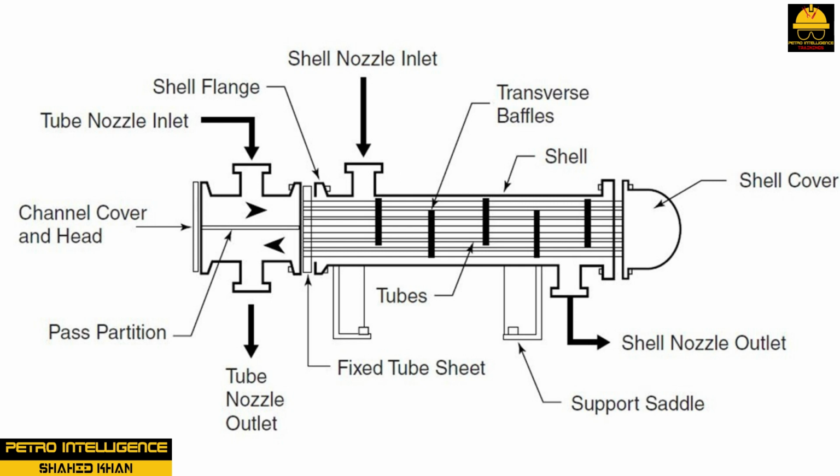A baffle installed in the head limits access to a portion of tubes on the tube sheet. As fluid flows through the exchanger, heat is transferred into or out of the fluid. After completing the first pass, process flow is directed back into another portion of tubes. This second pass across the exchanger allows additional heat transfer to occur.